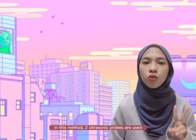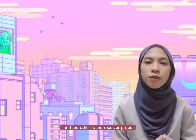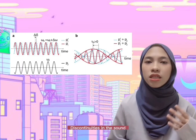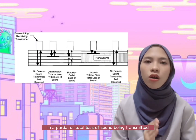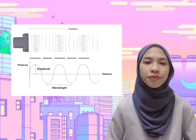In this method, two ultrasonic probes are used. One is the transmitter probe and the other is the receiver probe. These probes are situated on opposite sides of the specimen. Discontinuities in the sound wave may result in a partial or total loss of sound being transmitted and be indicated by a decrease in the receiver signal amplitude.